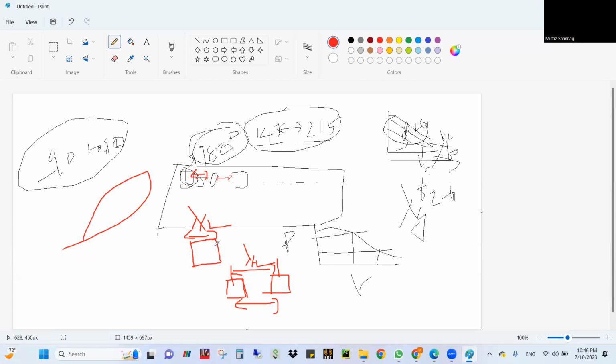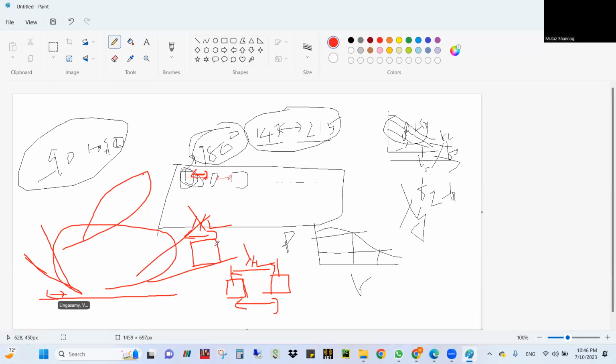For example, if you go beyond lambda by 2, or whatever it may be, you cannot steer the beam beyond a certain extent. That's why they compromise. For example, you want to steer the beam like this, like this, and this angle, there is one radar equation available. So optimizing this unit cell, the gap between the unit cells, will limit the beam direction, basically.